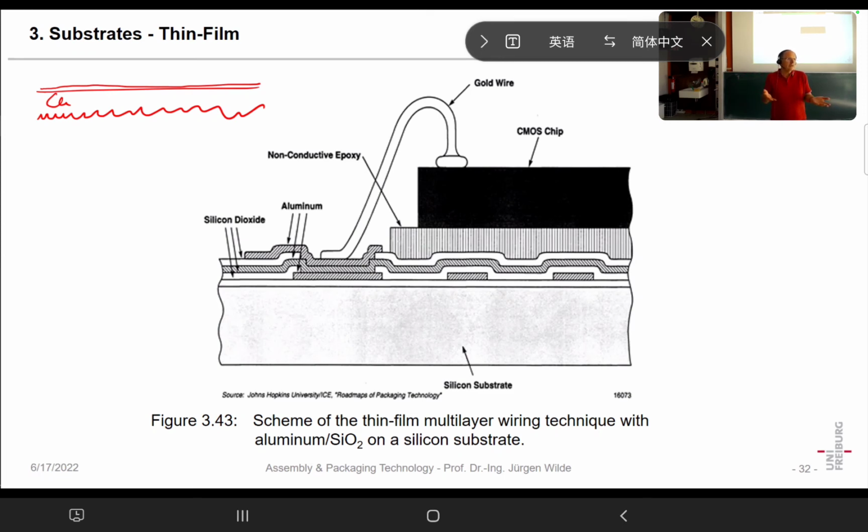You can also not solder a chip to glass or to silicon oxide. So you need another process, and a very well-suited process is conductive adhesive. So in that way, we can produce multi-layers, and as it is thin layers just stacked on top of each other, we do not need vias, but just by overlapping, we can come from one layer to the next.